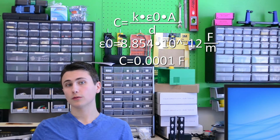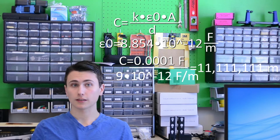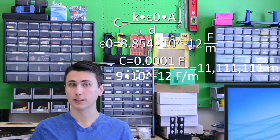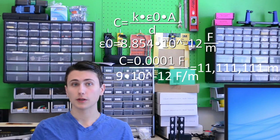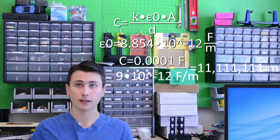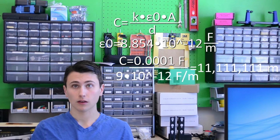The difference between these two numbers is a factor of 11 million. If we assume this is a parallel plate capacitor built in air, K is approximately 1. That means this factor must be achieved with the ratio between the plate area and the distance between the plates. Or in other words, the plates need to be really close together, really big, or both.